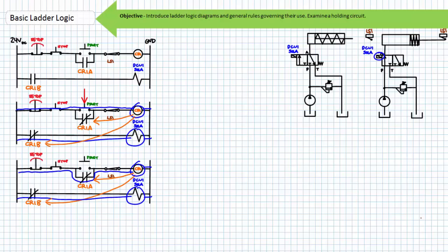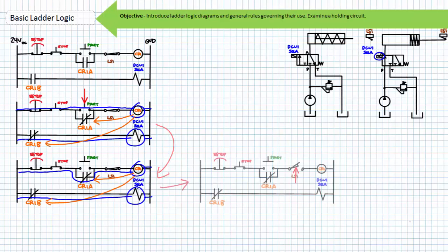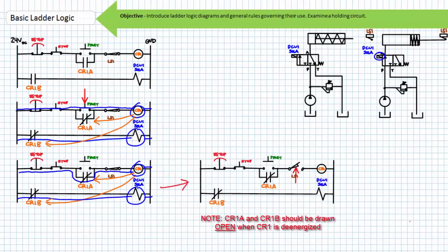One-cycle reciprocation means that when an operator presses and releases the start button, the cylinder rod fully extends, strikes limit switch 1, and then automatically retracts, marking a complete cycle without the attention of the operator. If at any time an operator wanted to stop the cycle mid-stroke and retract the cylinder, they can press the momentary stop button. This returns the system to its go state, ready to initiate another extension.